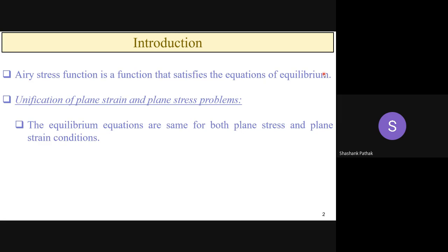That connecting link is very important to know, because Airy stress function is mainly devised to solve these plane elasticity problems. If you can unify the plane strain and plane stress problems, then you can very easily solve all the problems of plane elasticity using Airy stress function in one generalized approach.